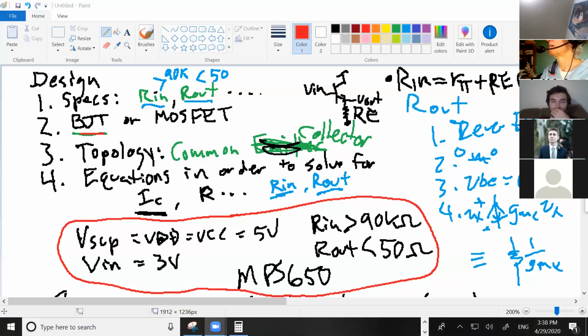The one circuit we looked at earlier where we did this was a diode connected transistor, and that was actually shorted. It doesn't have to be shorted. These are both ground, so it's like they're shorted anyway, but if the voltage across this resistor equals the voltage across the current source, then you get to reduce it to a resistor.